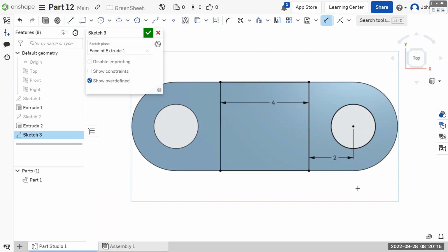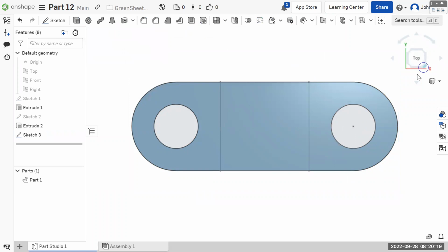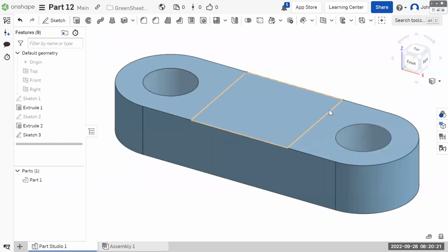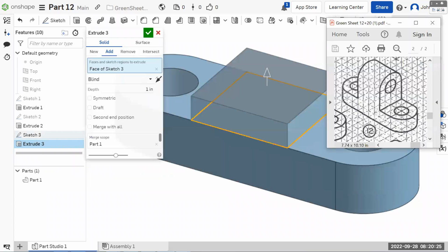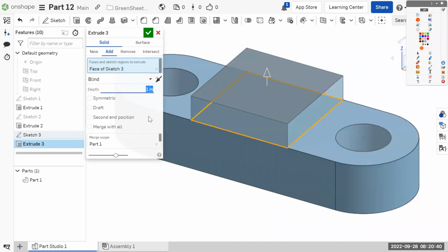And we have our base. Let's finish the sketch and extrude it up, which its height above where we are. We're extruding from this face. So it's 1, 2, 3, 4, 5 tall to get to the highest point. So let's put a 5 in there.